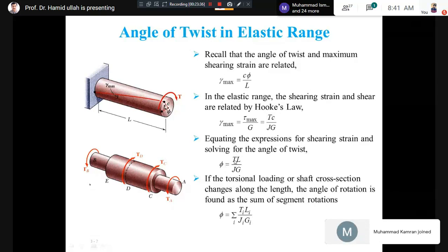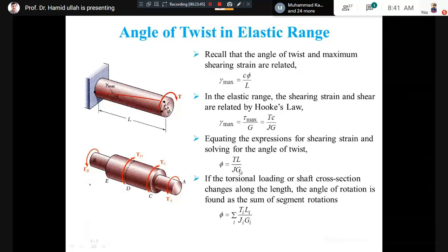Normal load multiplied by length divided by A, the cross-sectional area, multiplied by E. Why E? Because E is the material property when the load is normal. And you can recall that in the tutorial we saw that when the given body is changing in size, we use this formula, sum up the deformation for each section, and then for the whole body we sum up the deformation.